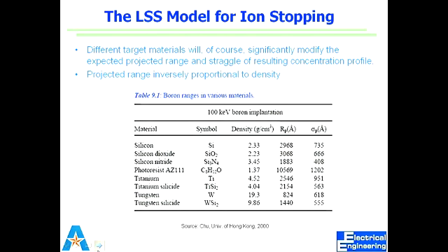So, okay, I know in boron at 100 kilo electron volt how deep it will go into one material, which is the projected range, RP, right? And then what would be the straggle, which is delta RP, sigma P, right? So now I want to use some material as a mask, which means that boron should not be able to pass through this guy, right? But of course it should go through this guy.